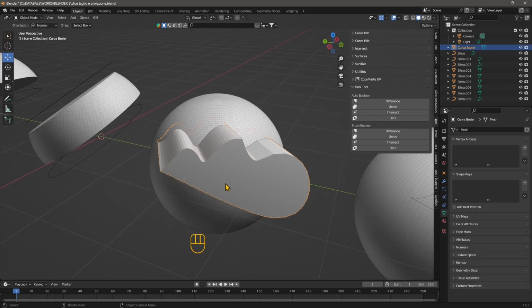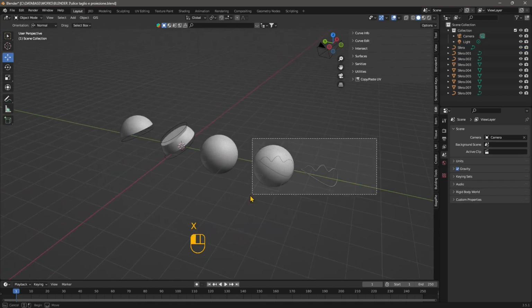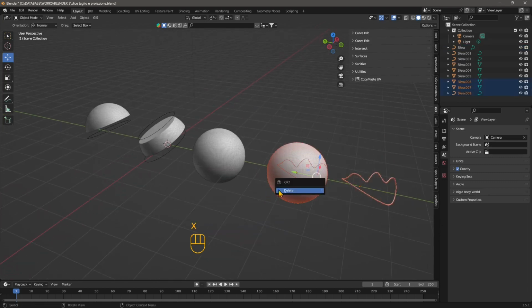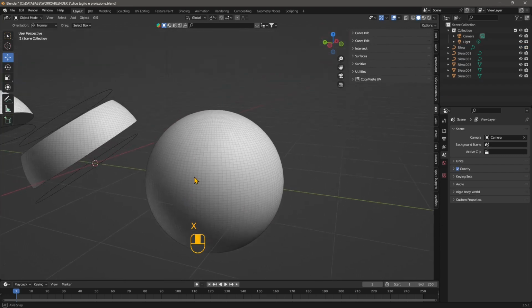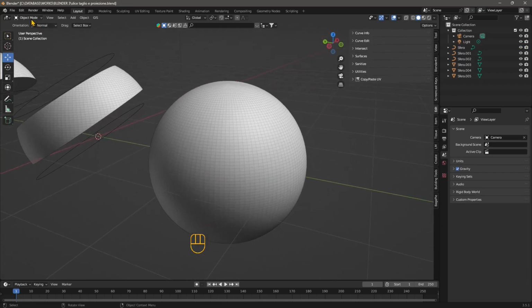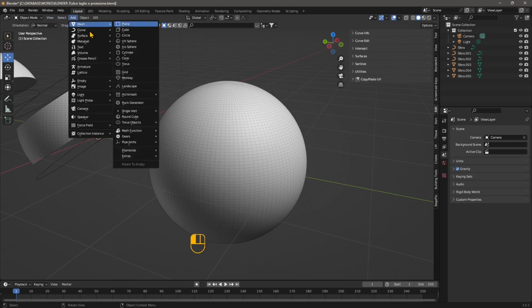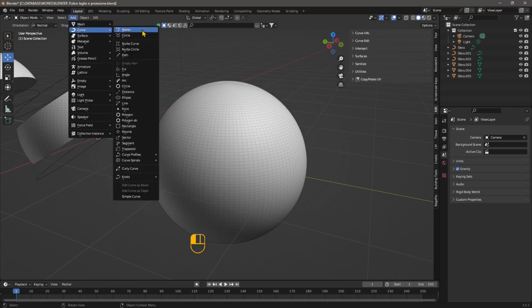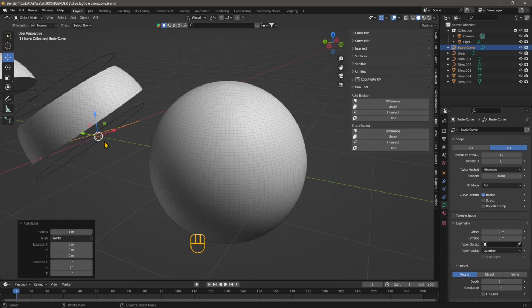So let's say I want to create a customized shape. I'm going to delete this one here and also the others right here. Okay, so when you use the draw mode, so first of all, let's add a curve, whatever curve you want. So let's go to add curve. Let's do a Bezier. Now the initial Bezier will be in there, near the origin.